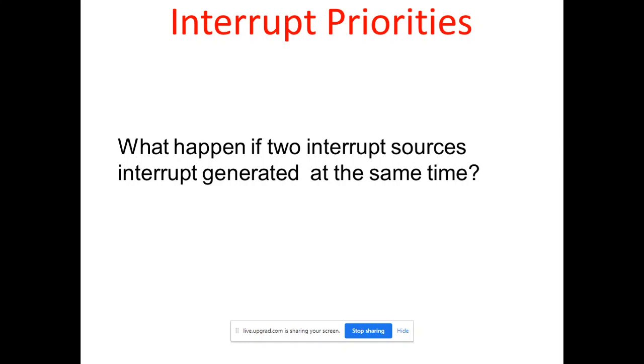If one interrupt source arises, the controller takes the starting address of the ISR and provides service to that interrupt. But suppose two interrupt requests arise at a time, what is the role of the controller? That is why the 8051 assigns priority to the interrupt sources. And what is that?